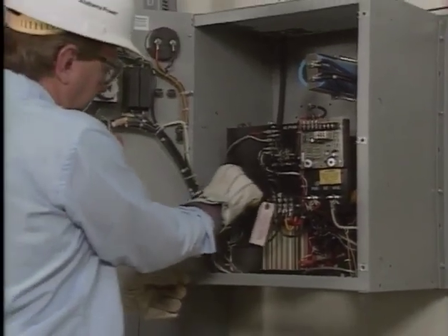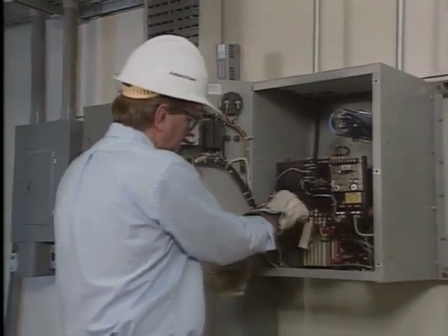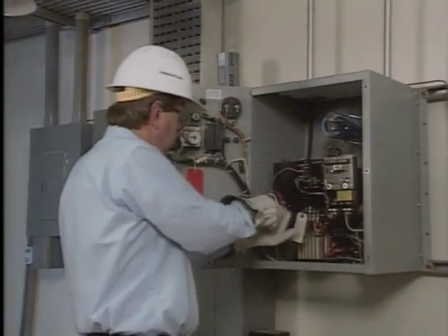Heating at the terminals is an indication of corroded or loose terminal connections. Any loose connection should be tightened. If necessary, the terminals would be cleaned using the appropriate tools and observing all other required safety precautions.